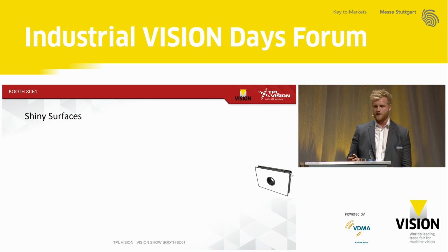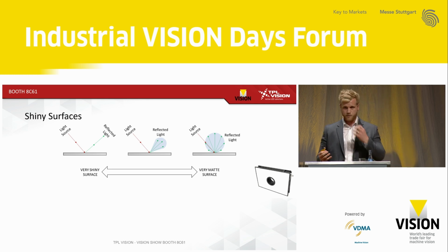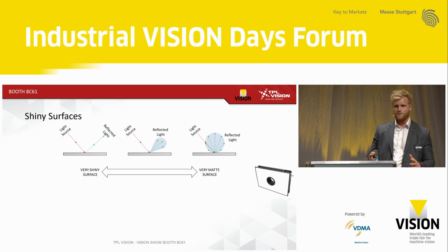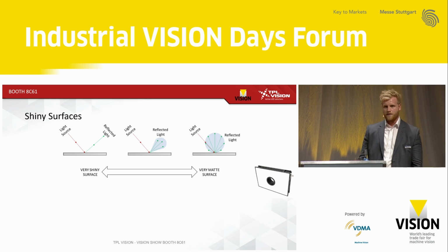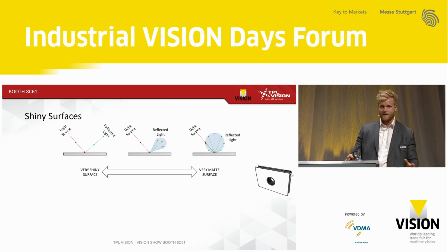So I'd say that this is not just a thing for pick and place. This is really a fundamental of machine vision, to understand how the light reflects. It's an important thing to know. Every time you pick up a light and you inspect a surface, you should always consider how exactly the light reflects off the surface. And if you think about it, you sort of follow the photons. It's probably the easiest way to figure out how to solve lighting problems.